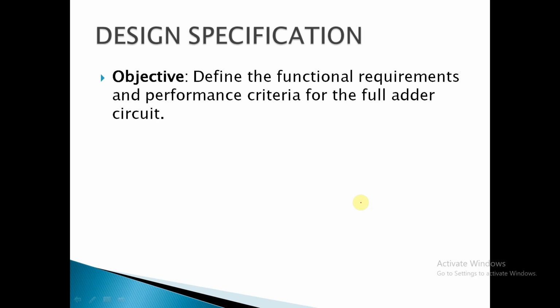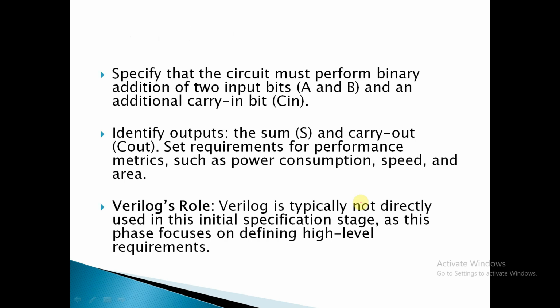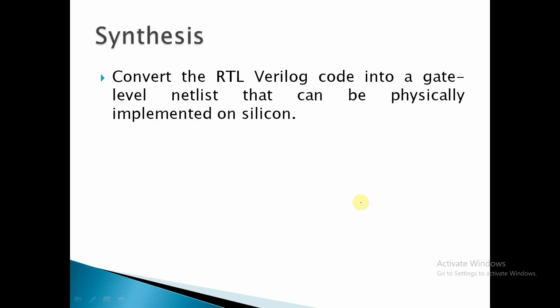So these were the definitions which I was saying orally. Design specification is nothing but defining the functional requirements and performance criteria. In this case, we are taking a full adder circuit, and these are the design specifications. We are specifying the inputs and outputs, and here the Verilog role is not much. Synthesis is nothing but converting the RTL Verilog code into a gate level netlist that can be physically implemented on silicon.